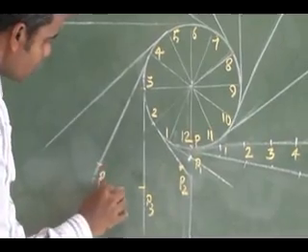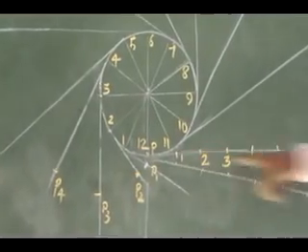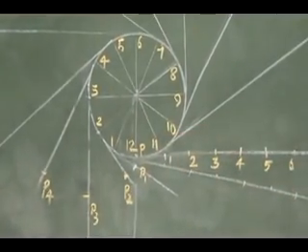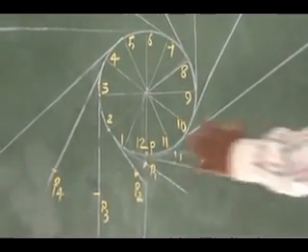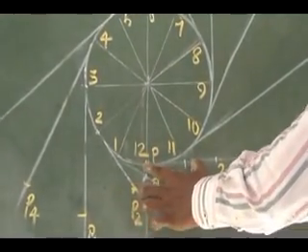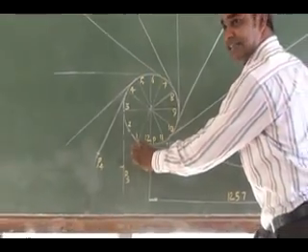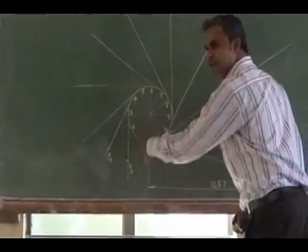So is it clear how I am marking these involute points? It's nothing but the divisions you have in the 12 divisions. Each segment length you know, you measure it in your compass. The first segment length you have to transfer from the first tangent line, the tangent line drawn from the first segment of the circle.